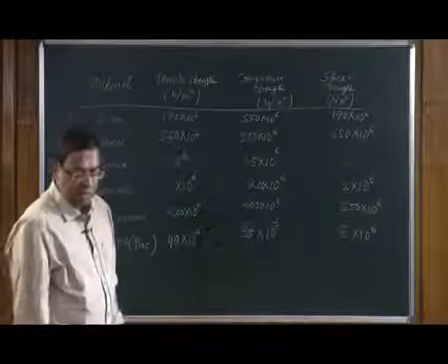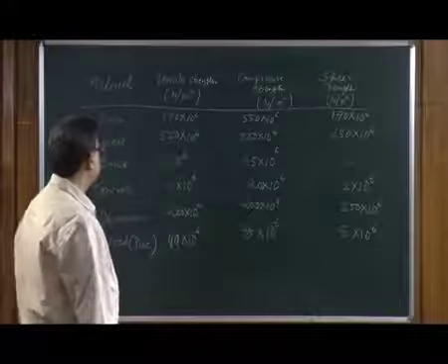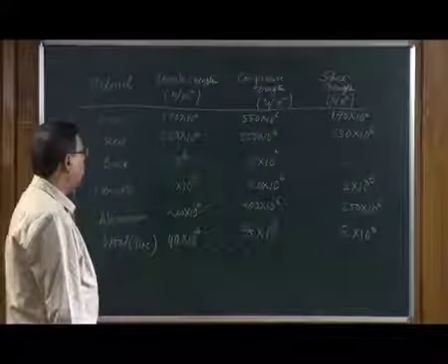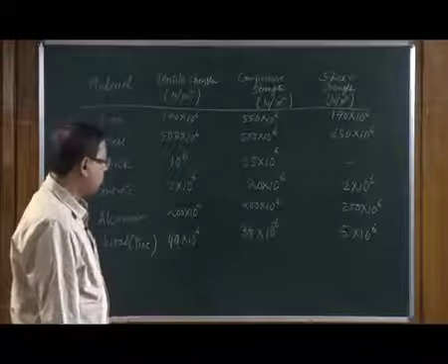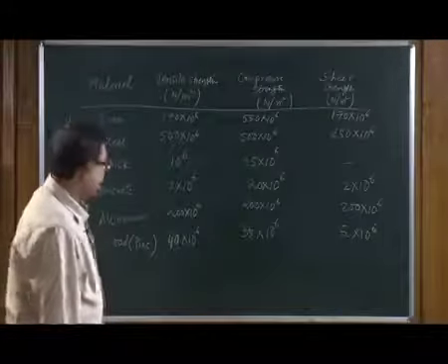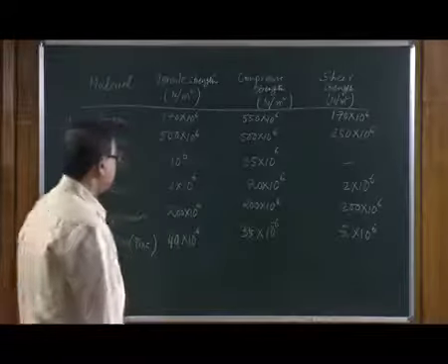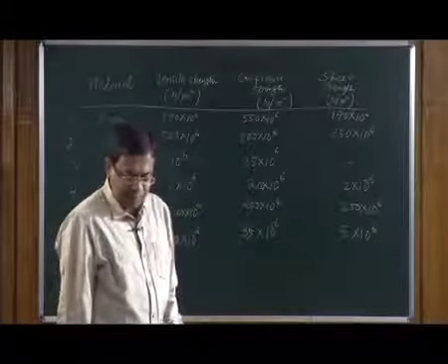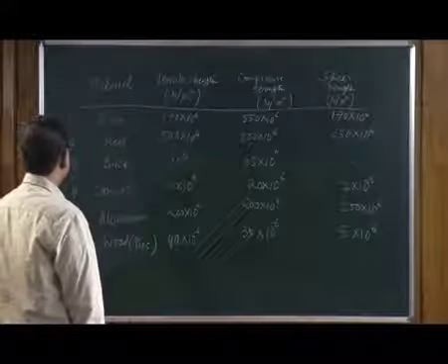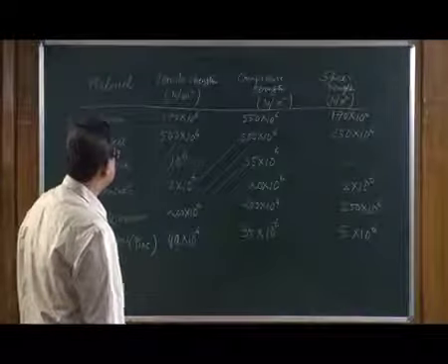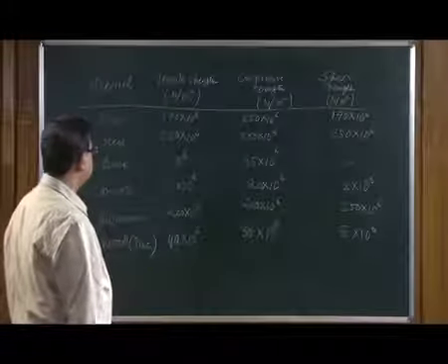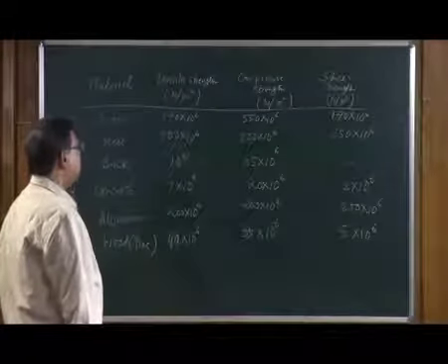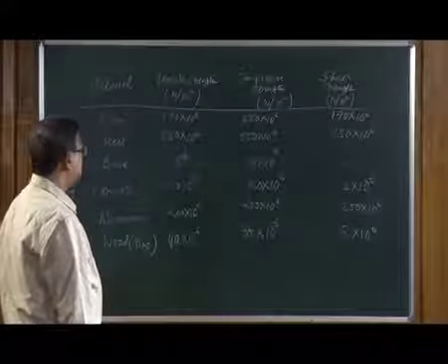And if one is making a structure with any of these materials such as iron, steel, brick, concrete, aluminum or wood, one should never cross these numbers. And in principle, while making structures, the stress should be something like 10% of these numbers and should not exceed more than that in any case. So, just to bring to your attention that iron has a reasonably large tensile strength, which is 170 into 10 to the power 6, whereas the compressive strength is more than 3 times of that, and the shear strength is again 170 into 10 to the power 6.